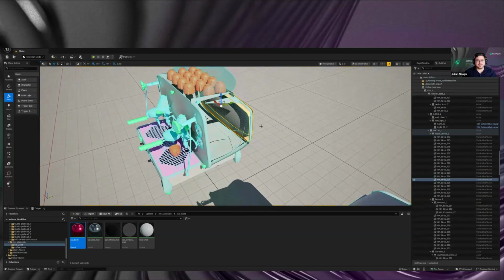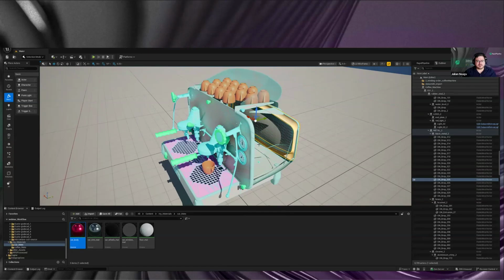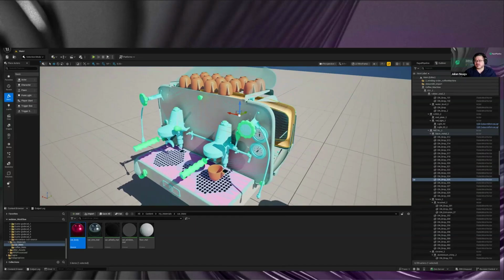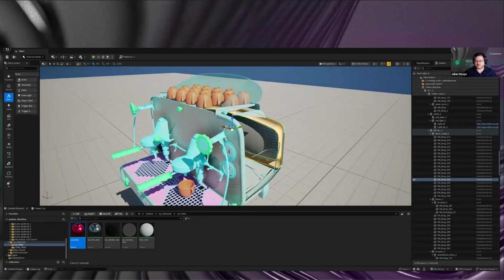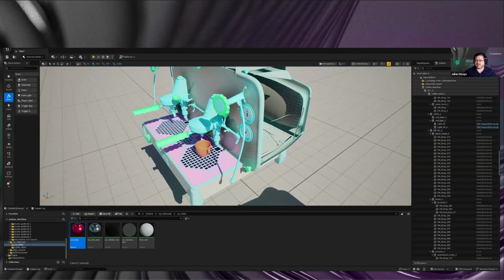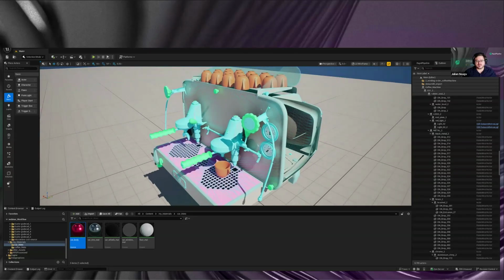And yeah, what can happen here is, and again, we're pretty certain that Unreal Engine also perhaps tries to do a winding order fix, so there's no exposed settings, so we might be wrong here. But usually software tries to fix those issues on import. But there are always files, as you might know, which have very specific problems, which just have duplicated surfaces or any type of interference where we will have problems with the winding order. And this coffee machine model here is one example for that.